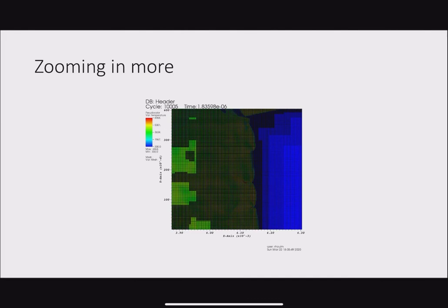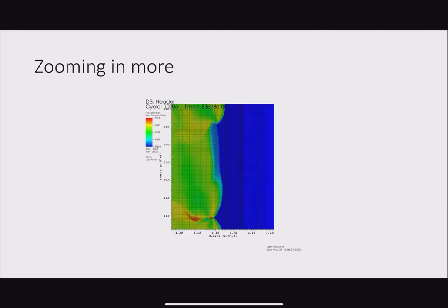And the reason that we make the finite control volume smaller and smaller is that the error introduced is a function of delta x and delta y. And the smaller delta x and delta y are, the more accurate the computation is. But the larger number of control volumes you have, then the more expensive the calculation gets.